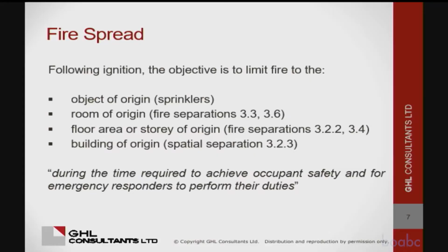Then to the room where it originated, again with sprinklers but also the fire separations, then into the story that it originated in, so it doesn't spread to other stories, so that's fire separations, and then to that building and not to the neighboring buildings, and that's your spatial separation. During the time required to achieve occupant safety and for emergency responders to perform their duties. Not forever, but for a defined period of time.